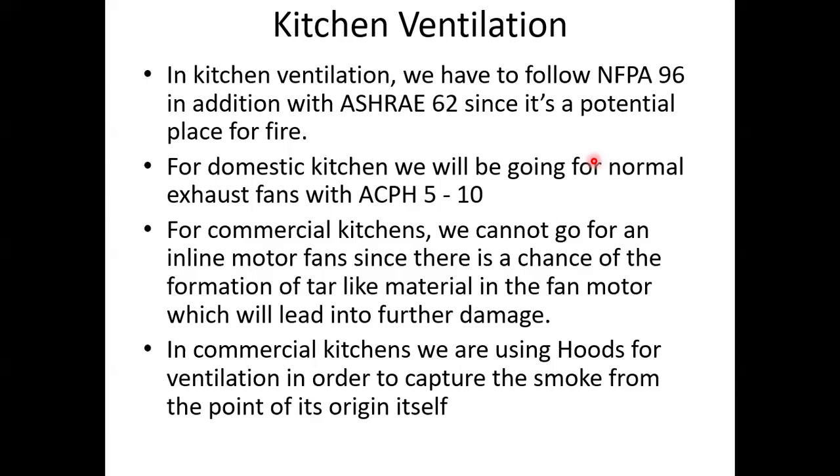So I will explain natural draft and forced draft. Natural draft means there won't be any fans. It should be naturally going, like hot air will always go to the top side itself. That's what I'm saying here. In commercial kitchens, we are using hoods for ventilation to capture the smoke from the point of its origin itself.